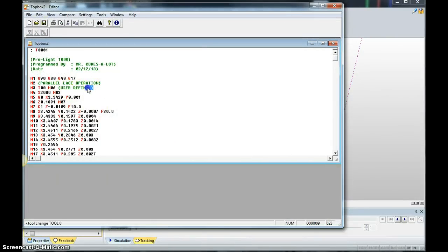And you're not done yet. We don't want to have a tool change, so let's get rid of this. Yours likely says N2, N4, N6, N8. That's fine. We're going to delete that. And what I like to put in here is a little Z 0.2. And really all that does is it makes sure that when you zero it, it's going to lift the bit up for you automatically before the spindle starts. My spindle speed changed. I don't know why mine did that, because I had set it to 5,000. So you might want to just verify that yours is set to 4 or 5,000. Either one of those will work fine for this. I'm setting mine to 5,000.